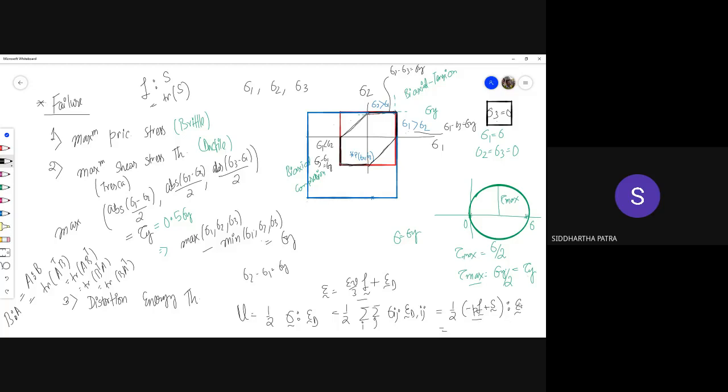So when multiplied with the corresponding components of epsilon and then adding them up, I'm supposed to get the trace of S, or the trace of epsilon d. So anytime you take the hydrostatic part or the volumetric part and the deviatoric part and do an inner product, you are going to get a 0. We explained that with the principal coordinate system, that they are literally orthogonal.